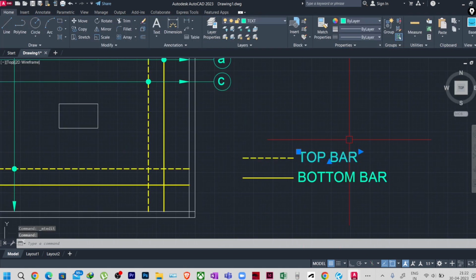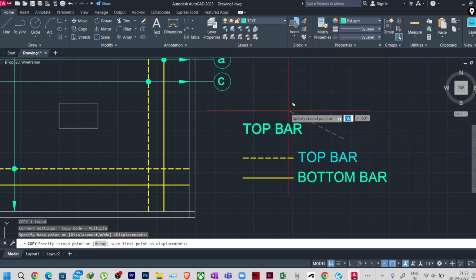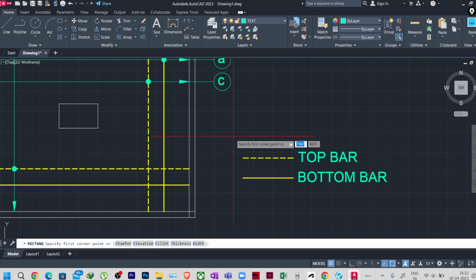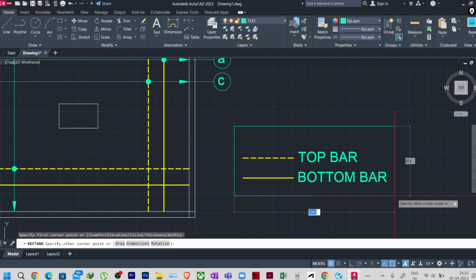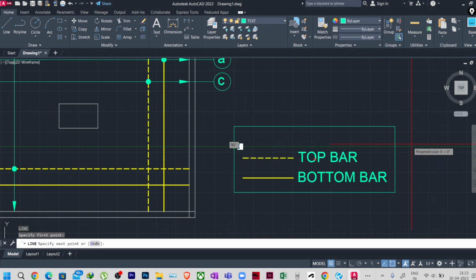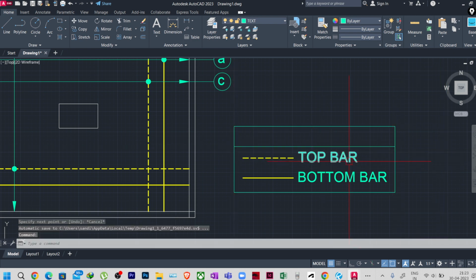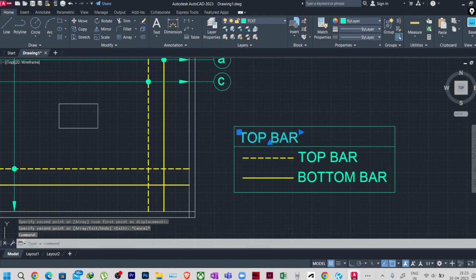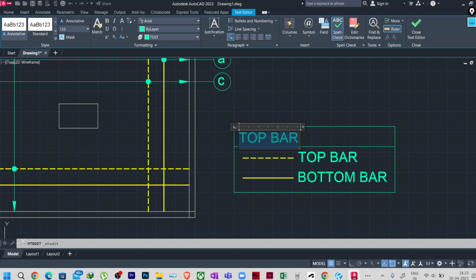And at the top you can write legends, CO, enter. At the top you can create a box actually. You just take a box like this, okay, you make a line here, you copy this, CO, enter here, and you can write legends.